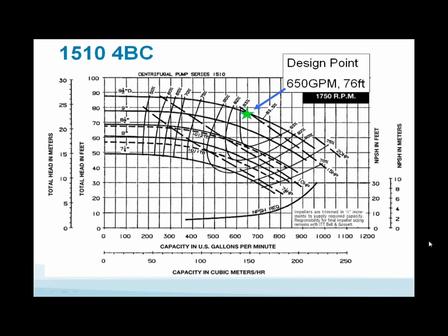Where are we? About 83% efficiency, midpoint. Beautiful selection of a pump. Great selection of a pump. Will the system run there? Let's turn the pump on and see what happens. So what size motor should we specify? By the way, I think I'd put a 20 on this to be non-overloading.